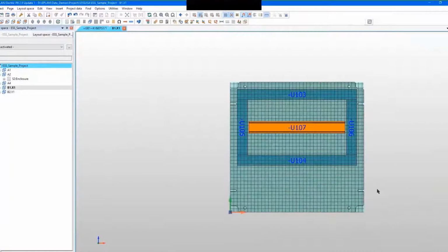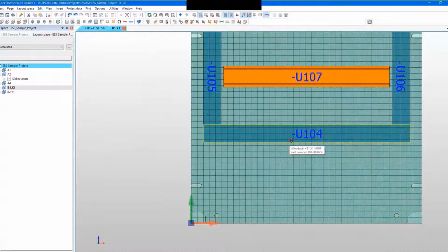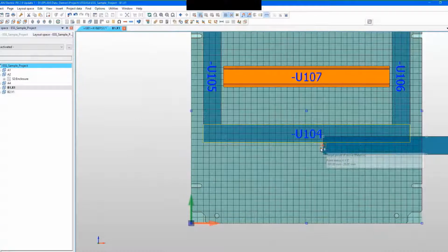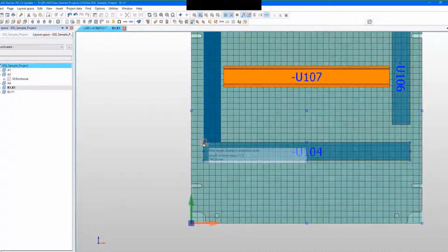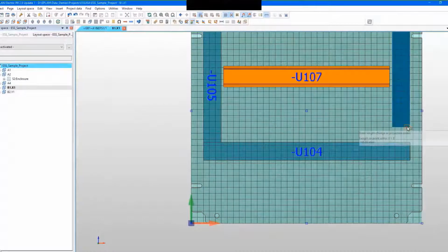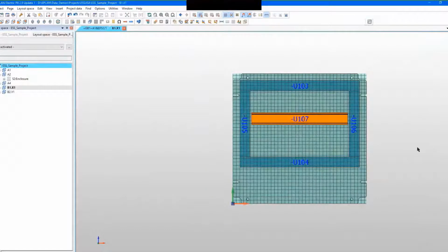So there's the ductwork. Now we need to start adding the components. And actually, maybe I want to move this down a little bit, so I'm going to move that down there, and I can adjust the length with my change length tool. I'll change the length of that one because I think I might struggle to fit the parts in. If you were doing it, you'd pay attention to what size of the parts were before you maybe made the ductwork.